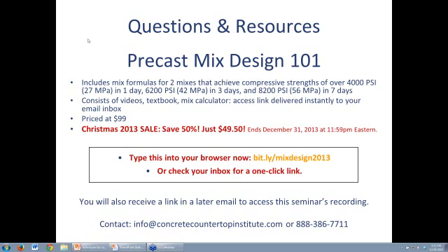If you had to make white concrete and you didn't want to go that route, I would use white Portland cement with titanium white pigment, possibly use a chemical accelerator, chill the concrete with ice to give you work time, and then heat the concrete as it's curing. So you kick in the accelerator, getting higher strengths. It's very complicated, but that's a good way to do it.